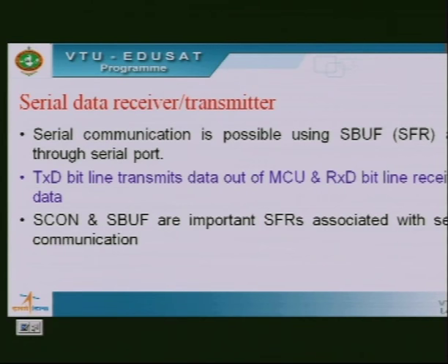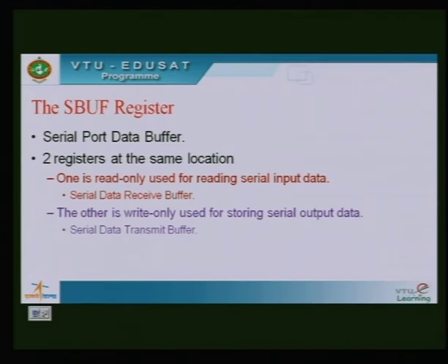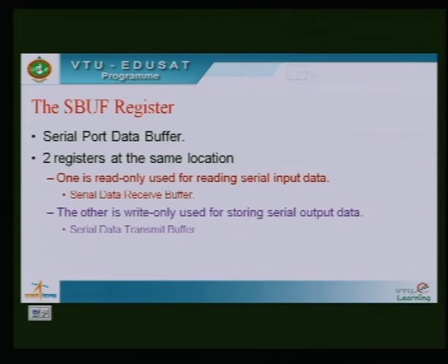So this is what I spoke of, two registers in the same location. One is read only, and that is called the serial data receive buffer. The other is write only, and it is called the serial data transmit buffer.